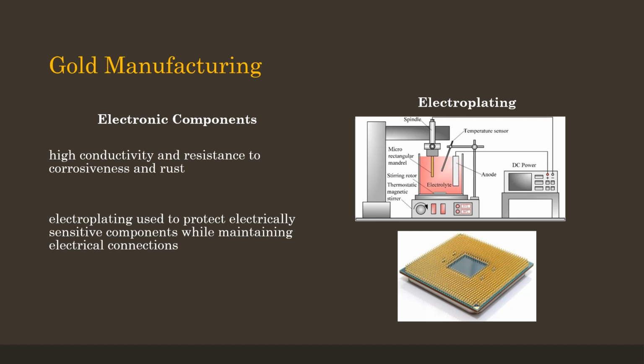the surface. The bath used in electroplating consists of an electrically conductive fluid, in this instance water, and a metal salt. Metal salt is what will be used to plate the components and is created from the reaction between a metal, and in this case gold, and an acid, usually a mixture of hydrochloric and nitric acid, usually in a 3:1 ratio. For certain components, a base layer may be necessary before gold plating.